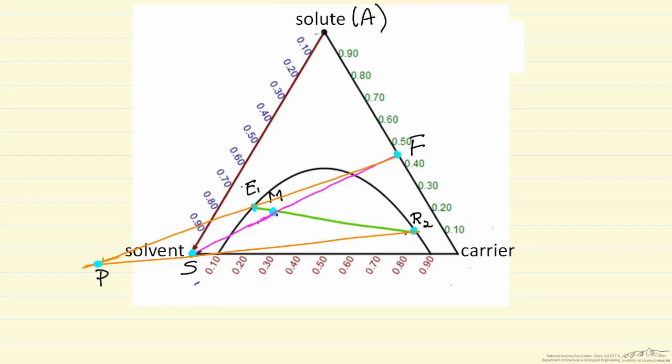I need the tie lines in this diagram. I've left them out just so it's less complicated, and for brevity we're not going to do the next steps, do that in a different screencast, but the idea here is that hopefully now you understand how we get the mixing point and the operating point just from mass balances, overall mass balances, and mass balances on the stages for liquid extraction.